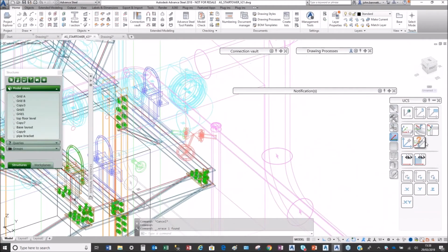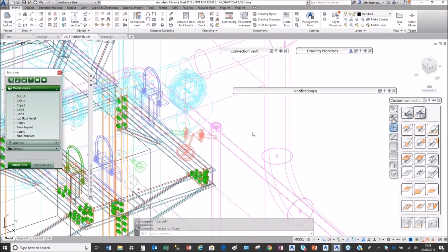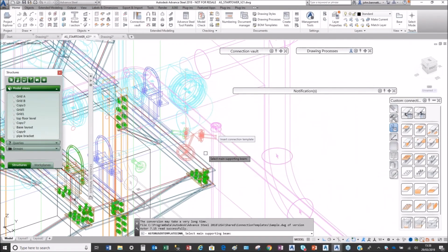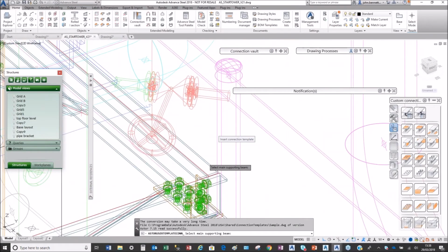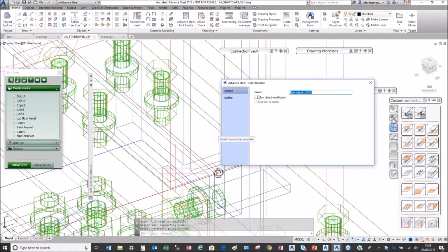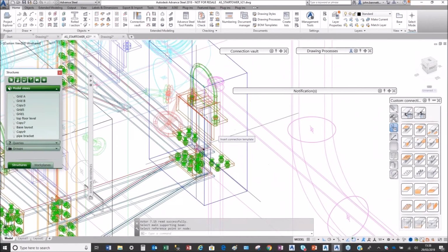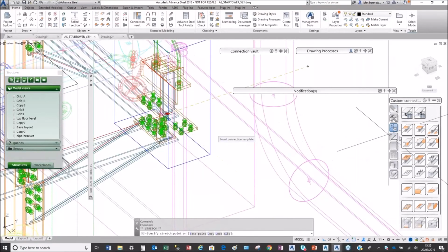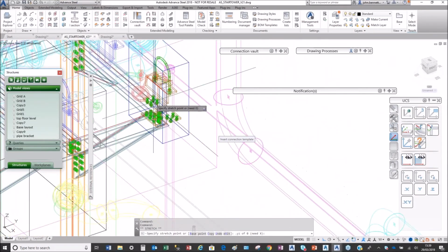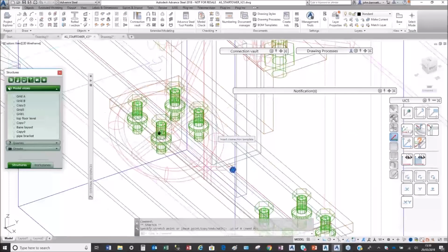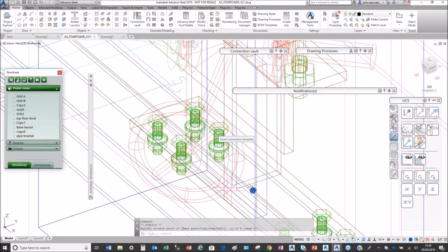So that was one variation. I can do the same thing here with the other pipe support that I created here. So I can do exactly the same thing. I can pick the main supporting beam. I can pick a reference point to bring it in. It might not be where I need it to be. And again, I can pick the reference node here and select it to drag it. Come here, use my snap filter again, and I'm picking the center of the pipe just to move it across. And we can see the bolts moving, okay, inside here.